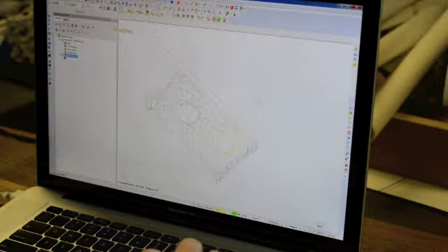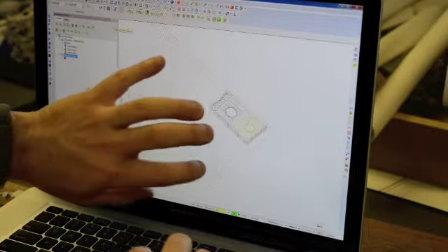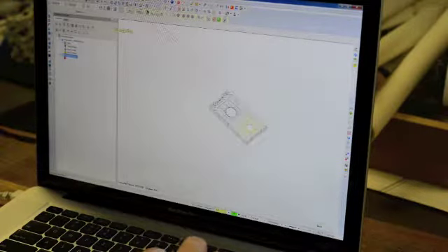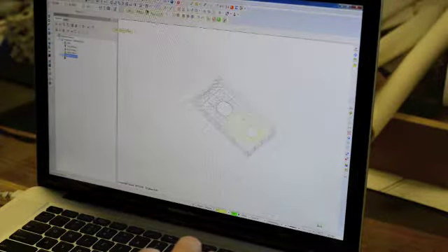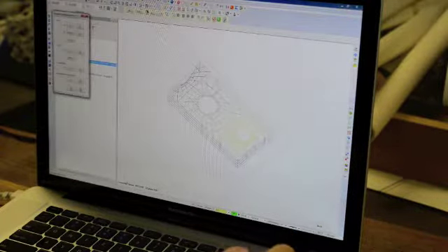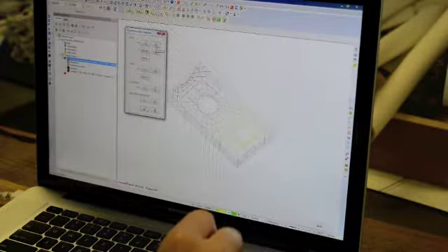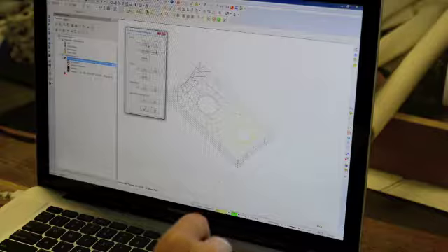So you have to, like I said, plan out how you want to mill this. So for example, if we were just milling this much and this was our whole stock, we wouldn't want to just cut out the part we wanted first and then do all the surfacing, because you'd want to be able to use all of this area to help hold down the part that you're actually milling. So that's why I'm saying strategize right here. So we picked our drive surfaces and hit enter, and then it's going to pull up this window over here. So this allows us to add or remove drive surfaces.